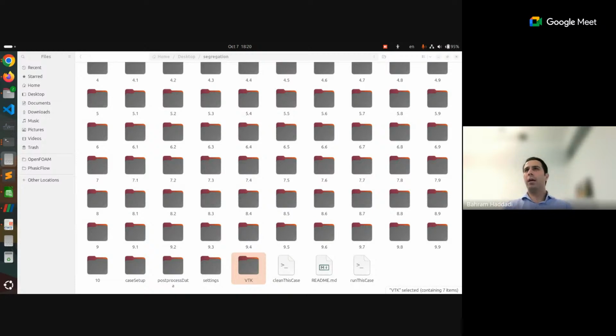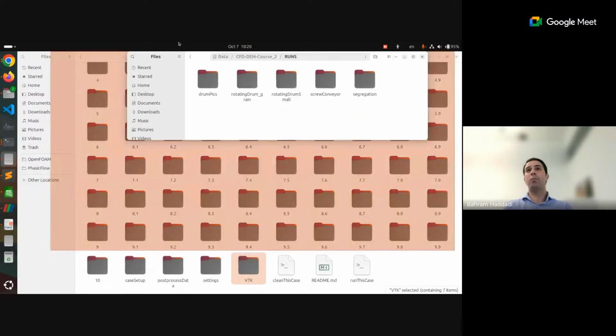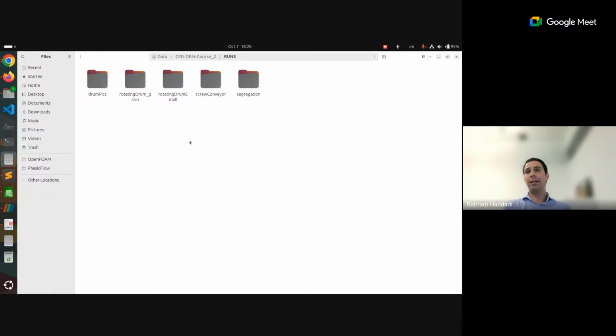One other point that I wanted to add here: when we are talking about methods like coarse graining, we are talking about bringing models into the simulation. And these are the points where, again, you have to be extra careful. You have to make sure that coarse graining is the right approach for what you want to do, because if you apply coarse graining to a simulation which is not suitable for that, that will lead to wrong results. You might ask me, okay, how should we know about that? My typical old answer is, go back to your physics knowledge, to your particle dynamics knowledge, and check if this behavior can be modeled by collecting a group of particles together or not.